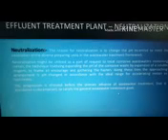So coming to the next topic, neutralization. What is neutralization? The purpose of neutralization is to change the pH value to meet the requirements of different processing units in the wastewater treatment system. Neutralization may be used in order to treat the acidic wastewaters containing metals. The technique involves increasing the pH of the acidic waste by the addition of alkaline reagent to form and precipitate and collect the precipitate.